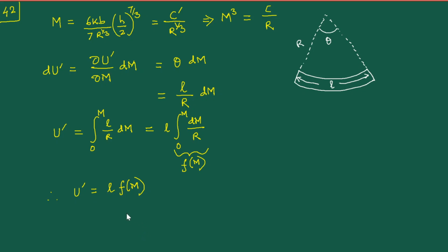Now what is the benefit of actually writing like this? The benefit is that with this understanding, if we have this kind of a formula for a length of the beam over which the radius is not changing, then in order to account for the entire length of the beam, we can just carry out an integration, but now considering that this L is actually like a differential element.